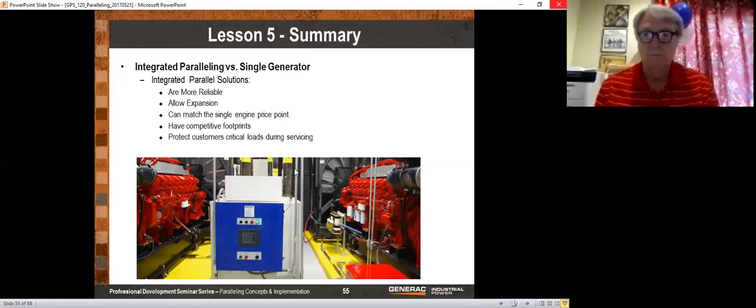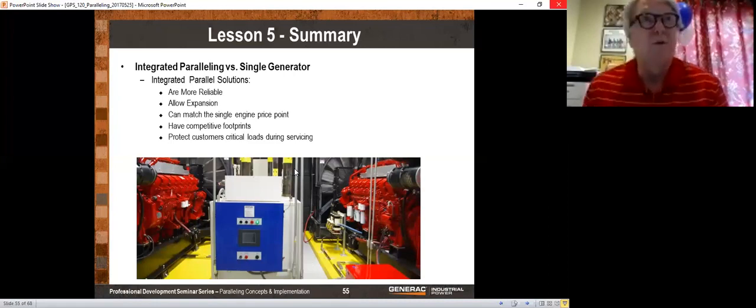Okay, last question here. Is there a minimum load percentage that generators need to be operating at? And does that often become an issue when paralleling? Yeah, it's never an issue when paralleling. Generators, all they do is sync to the voltage, and then once they close, they share the load. And so it's very, very common for you to exercise the generators. In that case, let's say you have 5 generators, you bring them online, you parallel them all, they all run at no load for half an hour, and then you shut them down. That's common. It's the most common way these things are done. So the load has nothing really to do with the paralleling.